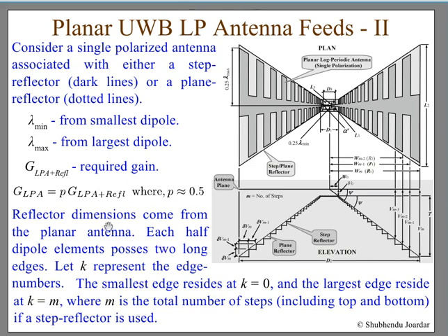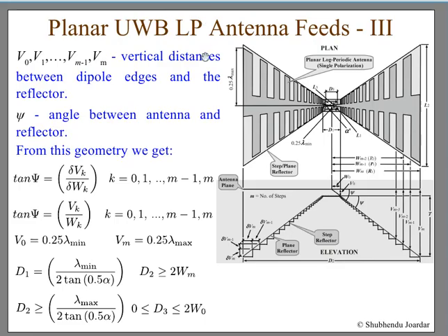You have to find the tau and the... The basic concept is you have to make a planar log-periodic antenna, and you have to use the reflector to flip the beam pattern on the other side. That is the basic concept.